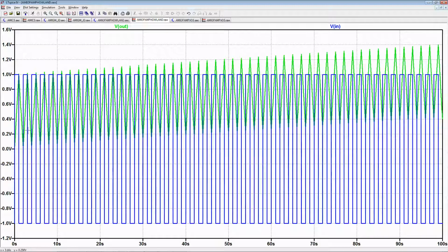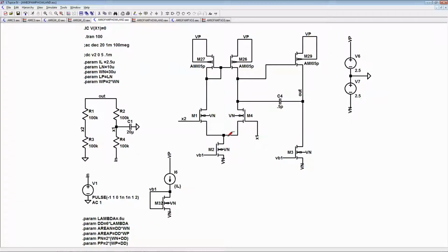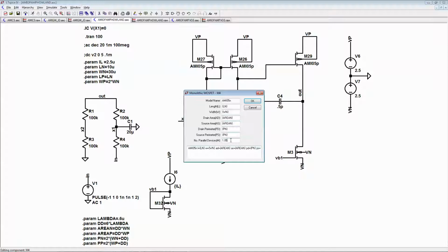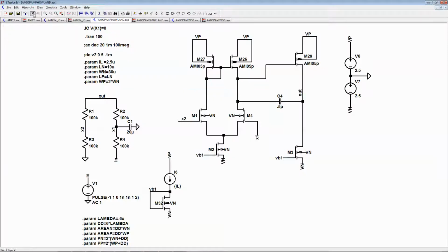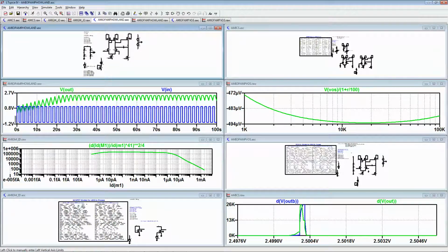So this is just kind of, I mean, yes, there's feedback, but in a way, that positive offset voltage is just being integrated over time, right? But every time there's a spike, right, it just gets reset. So it seems that this structure is pretty tolerant. Now, yeah, if I make one of them twice as big as the other, the drift happens very quickly, right?